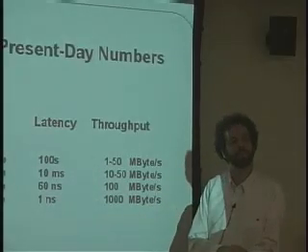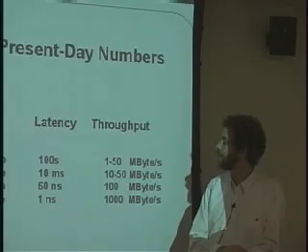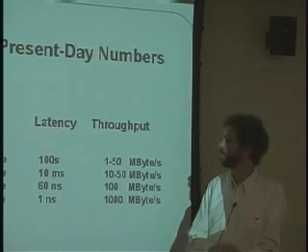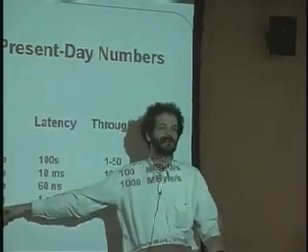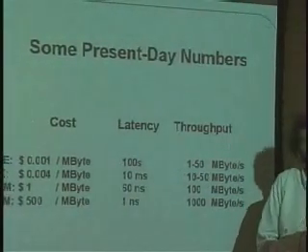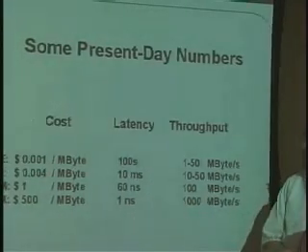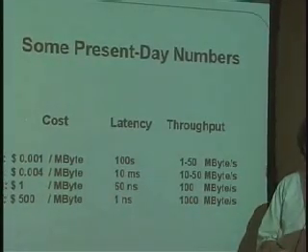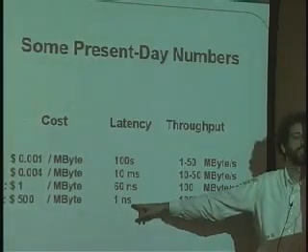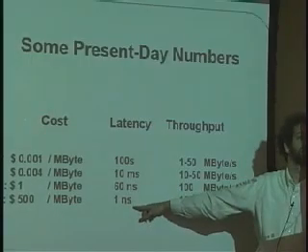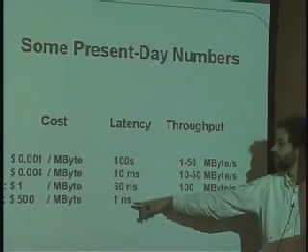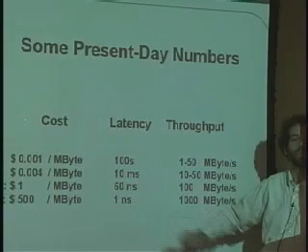Finally, we have this ridiculously expensive static random access memory. This stuff is typically on the actual chip that the processor is on. It's right there with it, and that's why it costs so much, $500 per megabyte, because typically you don't have a megabyte of it on the chip. You usually have a few hundred thousand bytes of it, and so maybe $50 worth of the chip is devoted to the cache, to the static RAM. And lo and behold, we finally have a memory system that can keep up with the voracious demands of the processor and give a word out every billionth of a second. You can make it even faster than this, but this gives you roughly the orders of magnitude for these things.